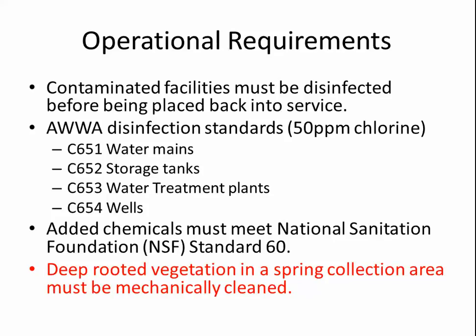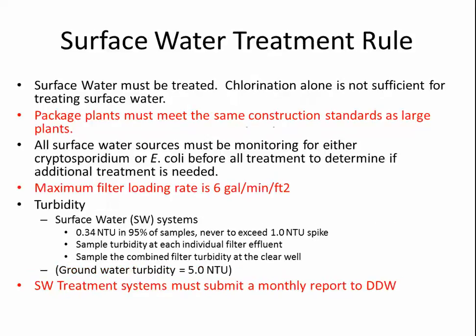And then this last bullet is in red because it's been known to be a question on the exam, and that is if you have a spring collection area with deep-rooted vegetation, that deep-rooted vegetation must be mechanically cleaned. It's important to remember for the test. Well, and also if you have a spring collection area.